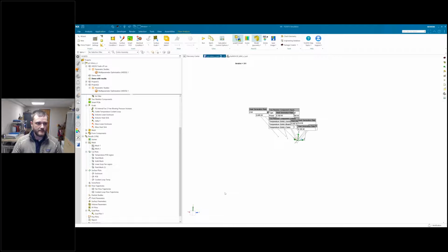All right. So here we have our package creator where we can create some really detailed models. Of course, it opened a bunch of them. Models of our ICs. And let's just say we want to create a new IC here. We have our recent ones, but we also have the option for all, whether it's a MOSFET or another type of IC. And let's say we want to just do a QFN here. And we can just give it a standard name. We'll just call this QFN2. And standard outline, we'll do a 4x4 millimeter and maybe 16 leads.